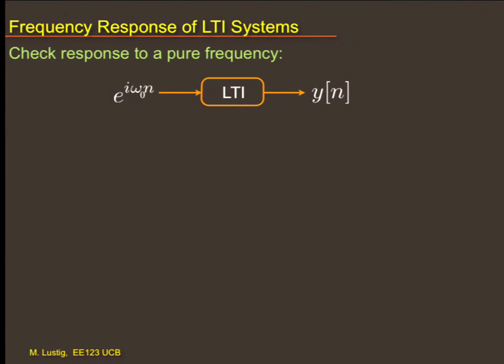And what is really a frequency response? There's a time response. Okay, that's pretty obvious. We talked about that. For example, an impulse response. LTI systems are characterized completely by an impulse response. If I know the impulse response, give me anything. Just give me something. I don't need to put it through the system. I know the impulse response. I know what's going to come out. Okay? Very powerful.